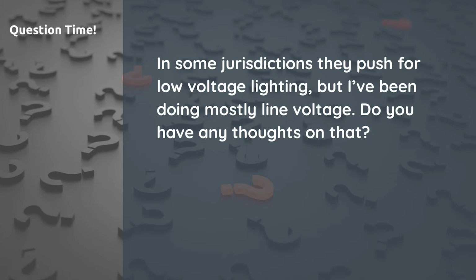Yeah, I do. That's a great point. We run into that, especially in the Pacific Northwest. There's a rule there that if you're not a licensed electrician, you can't even hang a transformer above 60 watts. For the most part, most of the transformers out there that are 150 or 300 watts have a pigtail on them. It's just like plugging in your computer or a TV. So to have a licensed electrician come out and plug into a wall seems a little excessive. Again, that does vary from municipality to municipality. Where I live, in the majority of the places I go to, you don't have to be licensed to install low voltage lighting.